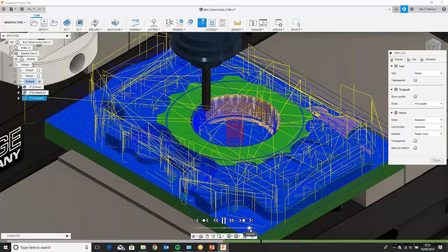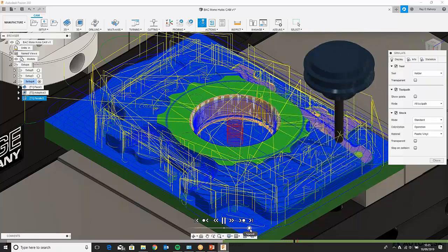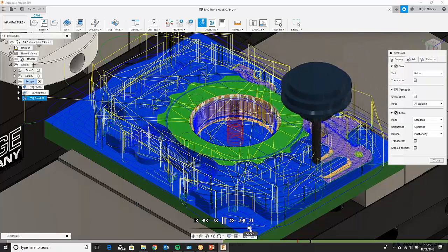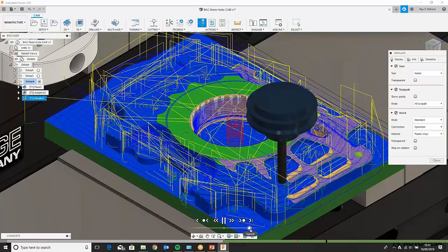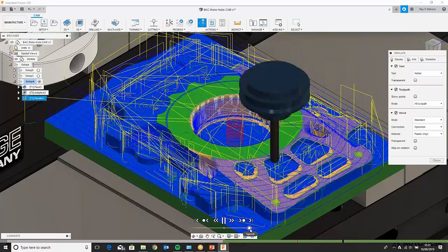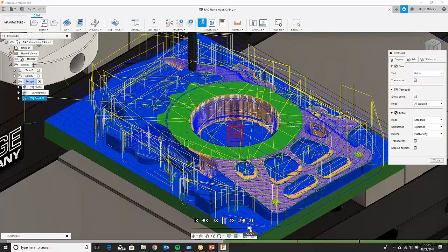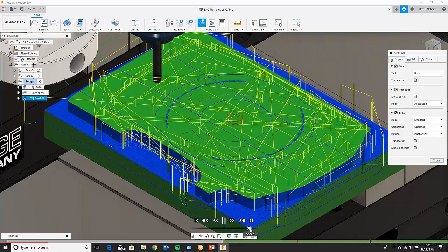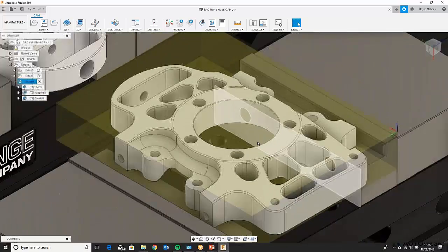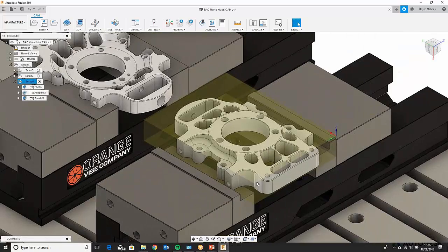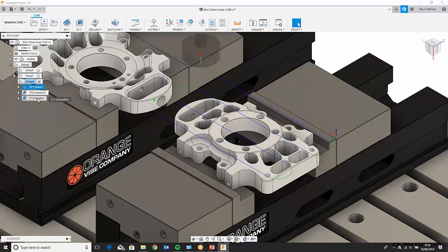Now, the big thing about all this really is that once I have this particular tooling information done, I want to be able to reuse this information again. I don't need to set up all these processes again if I have an operation on the underside of this part and I want to be able to reapply these operations without going through the necessary setup again.